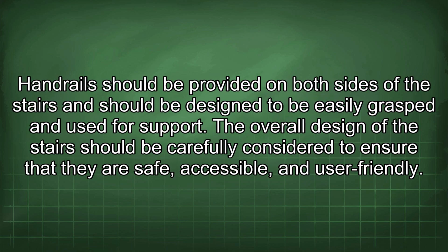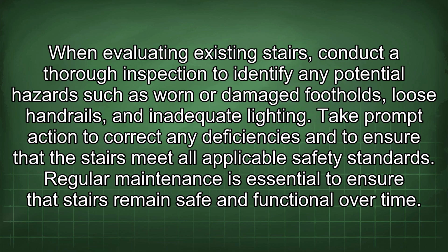Handrails should be provided on both sides of the stairs and should be designed to be easily grasped and used for support. The overall design of the stairs should be carefully considered to ensure that they are safe, accessible, and user-friendly. When evaluating existing stairs, conduct a thorough inspection to identify any potential hazards such as worn or damaged footholds, loose handrails, and inadequate lighting. Take prompt action to correct any deficiencies and to ensure that the stairs meet all applicable safety standards.